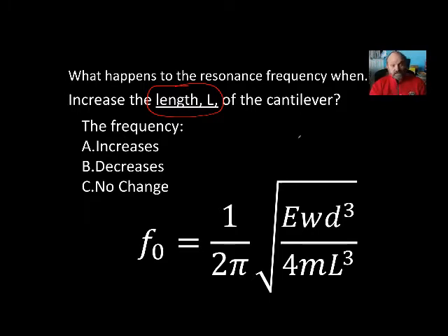I usually do this live in the classroom, and you'll find out that the longer it gets, the slower it gets. Now, if you look at the math, that makes sense, right? The length of the cantilever, L, is in the denominator. So if this goes up, right, the frequency will go down.